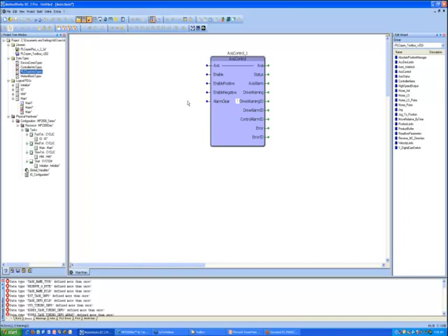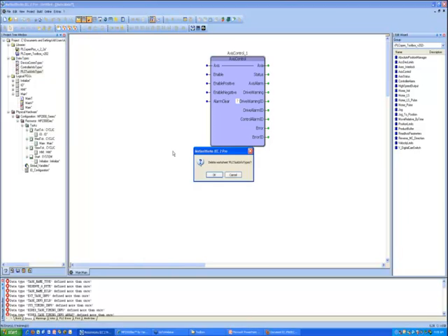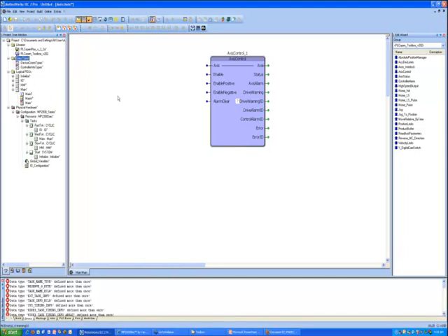So anytime you're using the PLC Open toolbox, one of the first things you have to do is delete the motion block types from your main project, and also the PLC task info types, because we already have a copy of these definitions. And if I hit compile once more, we're down to simply one error, which I do expect because I haven't included the math toolbox, as I was mentioning earlier. So I'm going to go back and add that one as well.